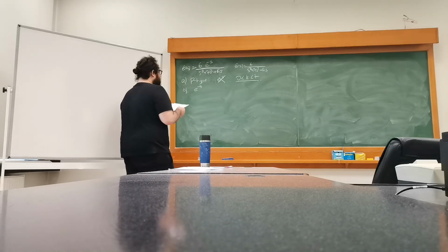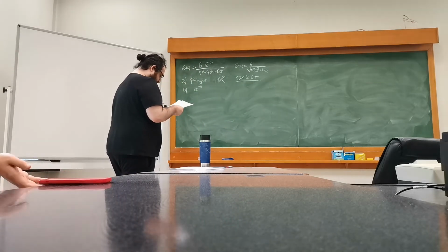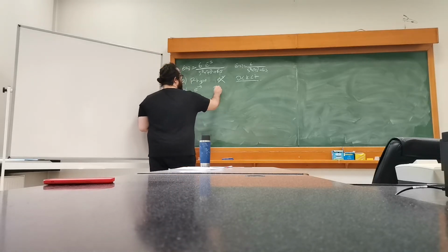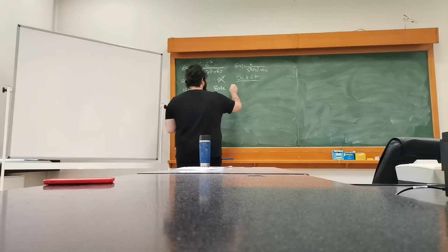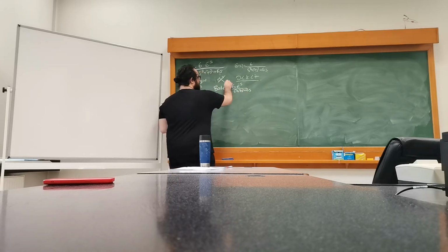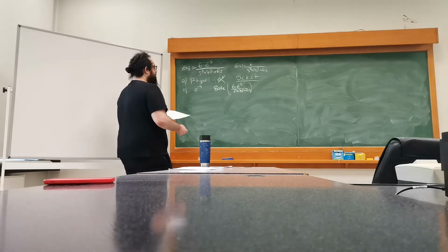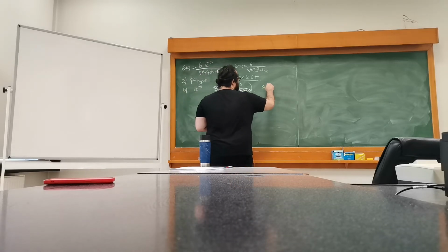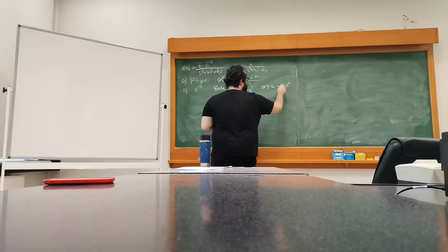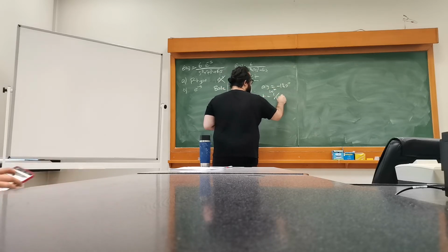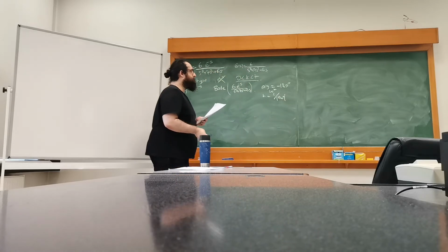Now, what about adding a certain delay value? Again, if we have the Bode plot of the whole system, 6e to the power of minus s divided by s cubed plus 7s squared plus 6s, it's not really that big of a deal, because we will look for, again, the argument should be minus 180 degrees. At that frequency, we will get 1 divided by G(jω). And that will be it.